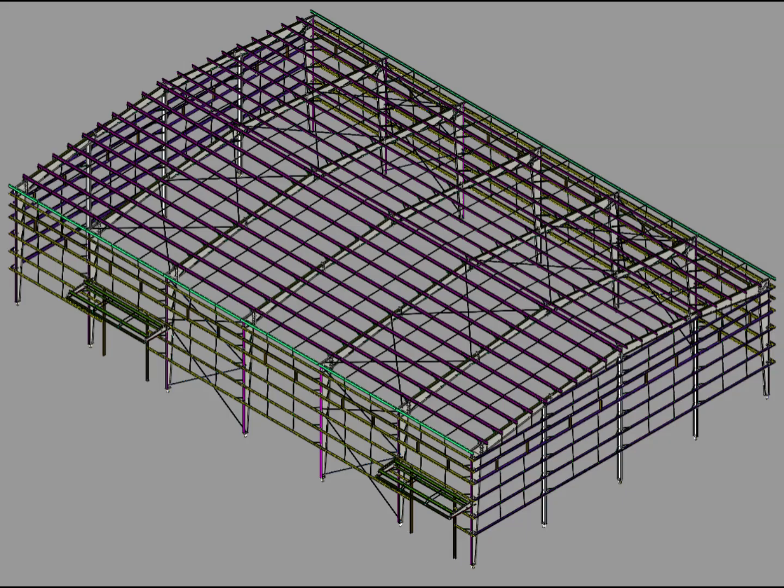In our real PEB project, the roof framing drawing specifically identifies sag rod along with other roof framing components. That gives us a practical opportunity to understand how this small member is represented in an actual engineering drawing and how that information translates into a real three-dimensional PEB structure.